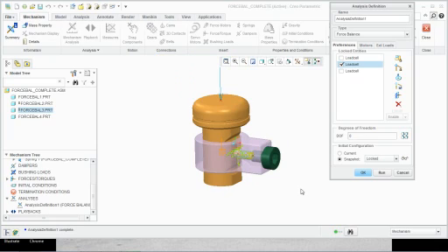Now, where is this really helpful? Say, for example, you have shock absorbers, right? I'm going to go through a bump and I don't want the shock absorber to move. So I fix the location, I create a load cell at the piston top. When I go through the bump, I enter a force. It tells me what the reaction force should be at the other end of the piston to stop the piston from moving.